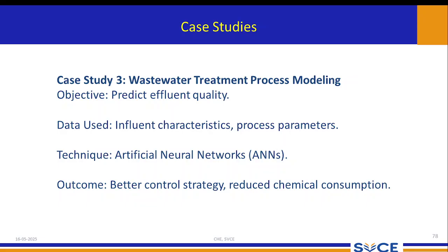Let's say I give you the advanced oxidation process in wastewater treatment, by adding ferrous sulfate and hydrogen peroxide. The main objective of treating the compound with advanced oxidation process is that compounds which are not easily degradable, recalcitrant in nature, can be degraded by adding ferrous sulfate and hydrogen peroxide, because when you add these compounds, they form a hydroxyl radical.